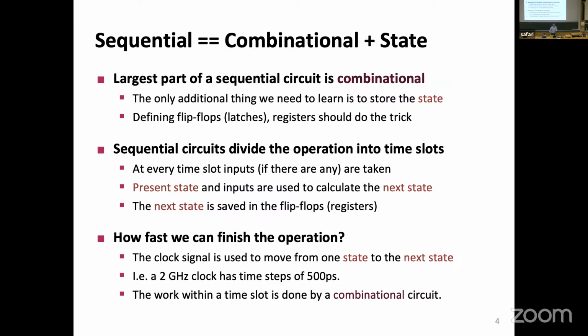It's difficult. Okay, so once again, sequential circuits will mean combinational circuits, which we already know, plus state. This makes our lecture today very, very easy. We will just learn how to define the state, and then we go home. The only additional thing is to store the state. So we will have things we call flip-flops. There's a lot of Californian terminology in digital circuits. Latches, and something we call registers, which is a collection of them.